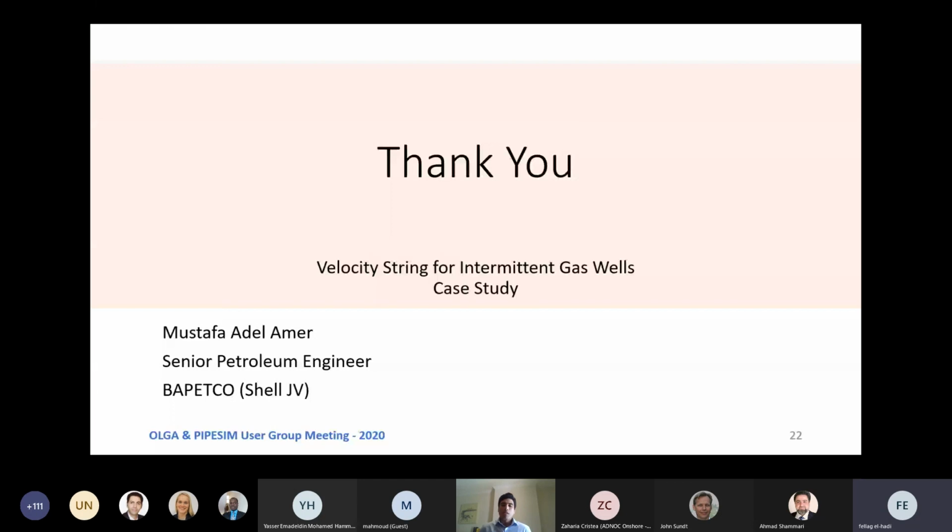Choosing the wells depended mainly on the operational risk. So we chose wells that don't have problems in the existing 5-inch completion, in the area below the subsurface safety valve and at the end of the tubing. That was one thing. The second thing was the potential. If we insert the 2 7/8 completion, are we going to have a good rate or not?